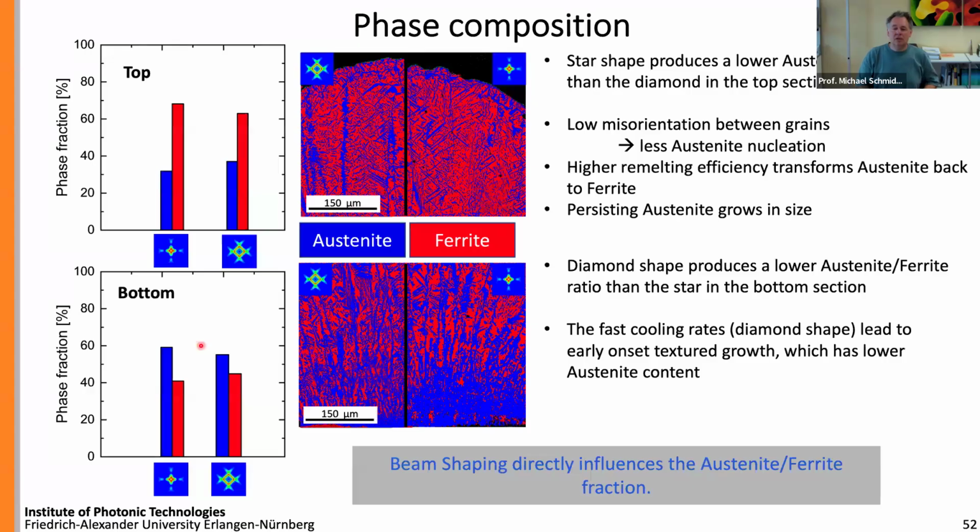This is, by the way, no wonder, because you might also experience, if you build a part, let's say, by powder bed fusion out of a certain material, and you want to heat treat the part, and you do the heat treatment via the heat treatment book that is 50 years old, so let's say the standard heat treatment, the resulting microstructure might not be the desired one because your starting structure was a different one.